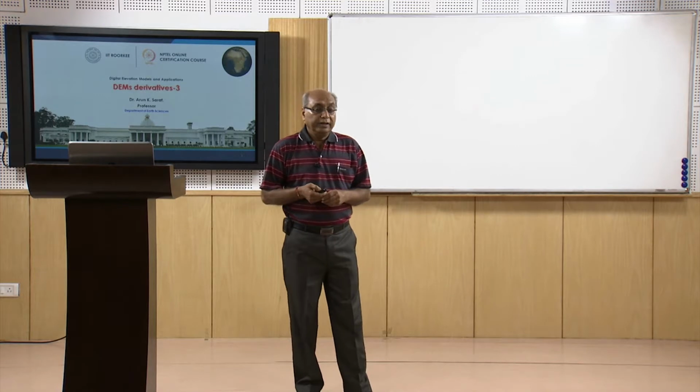So based on this, if it is too high, we can classify a landform as a hilltop or a ridge. Significantly low values suggest that if we are getting a very low TPI value, then probably we are near the bottom of a valley. So this is how the interpretation of a TPI map can be done.